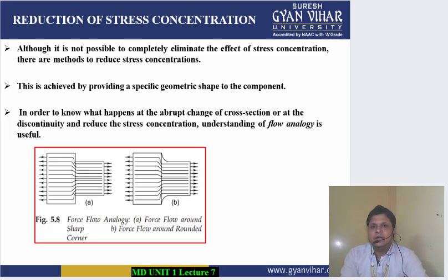Streamlining or rounding the contours of mechanical components has a similar beneficial effect in reducing stress concentration as we see in the case of flow phenomena. Here in stress concentration also the same can be used because there is some analogy between the equations. The equations used in fluid phenomena and the equations used here in stress considerations are more or less the same. Therefore, since we do streamlining in flow phenomena, in stress also we can do the same thing.